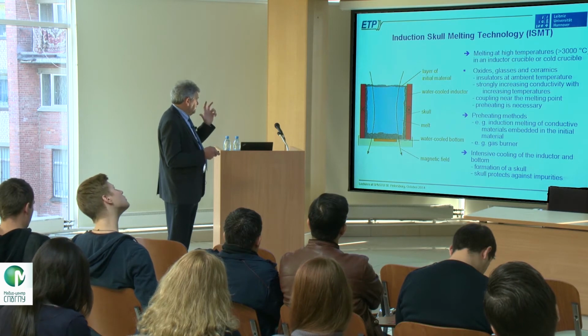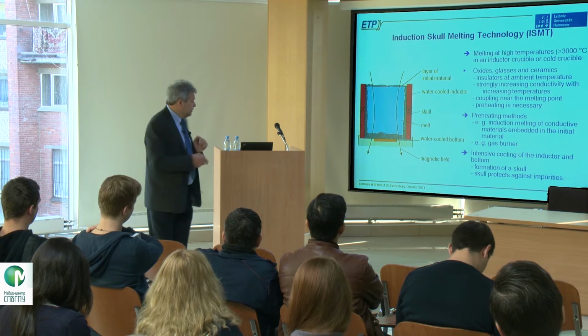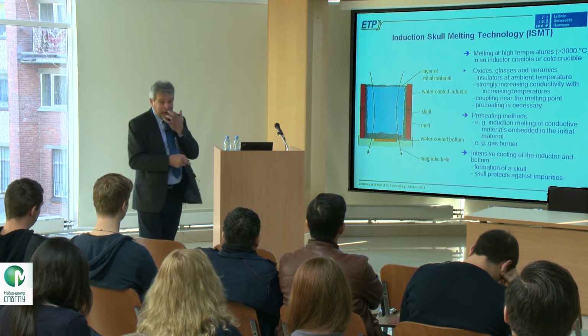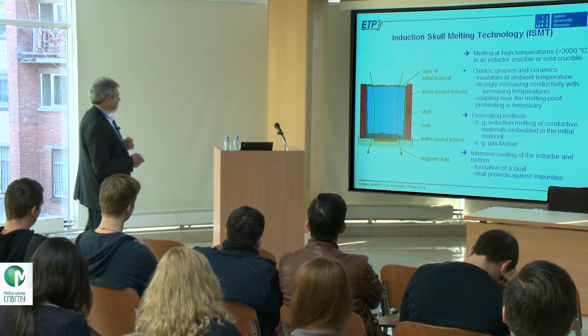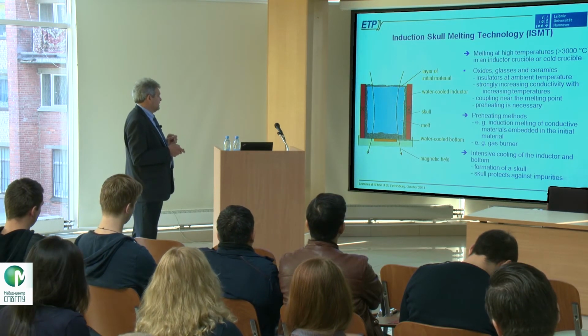And of course, as I told you, this skull protects against impurities. It even makes the melt purer than before, because if there are some impurities, they will stick on the surface of the skull. Very important for glass, for high pure glasses.